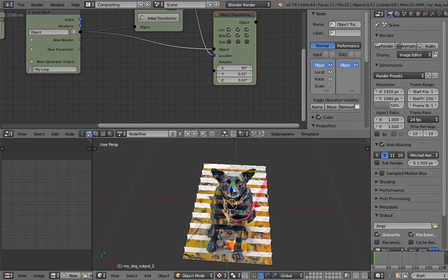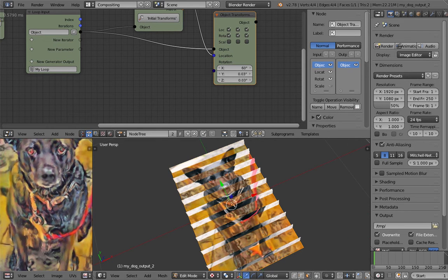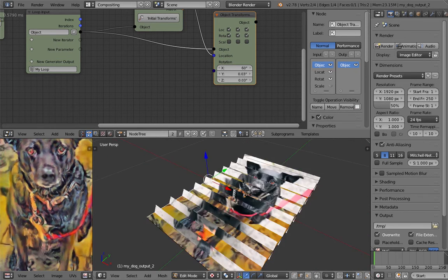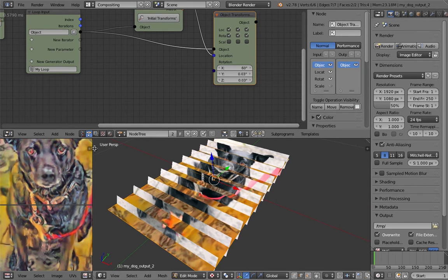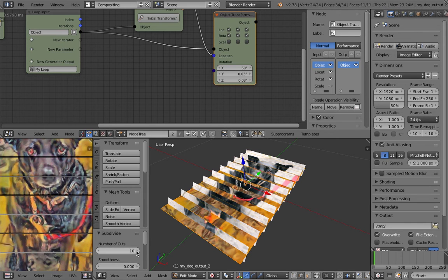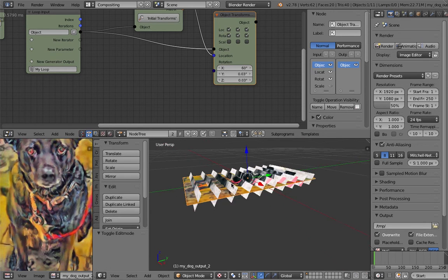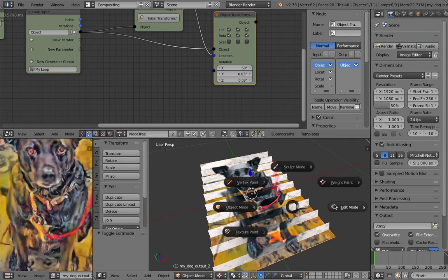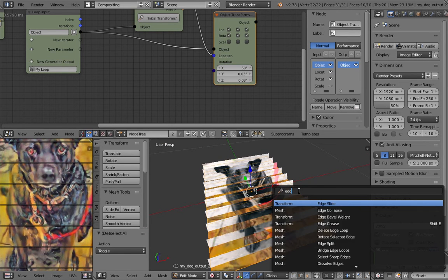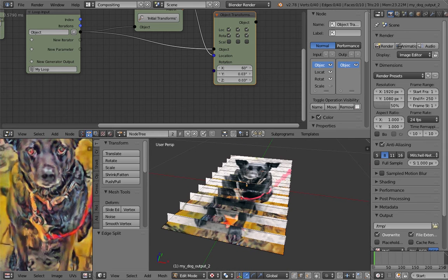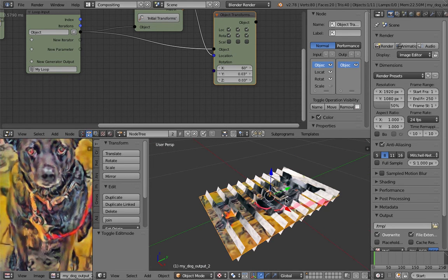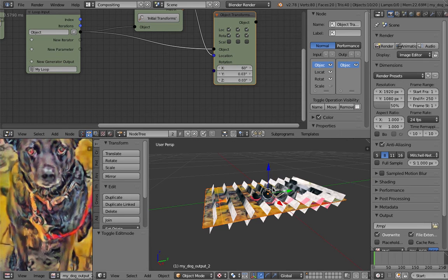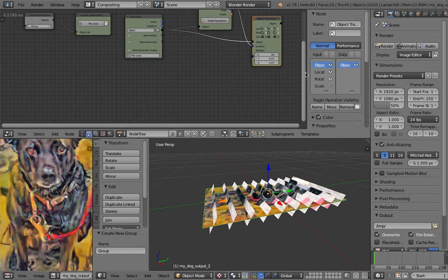Let's do the same thing, edit mode, and then go to edge selection, select the edge, and then subdivide, cut it by 9 times, so we have 10 separate, and separate, actually edge split. Now if we select the face, it's already working. Select this guy and separate loose, and then group it. Okay, done. That's done.